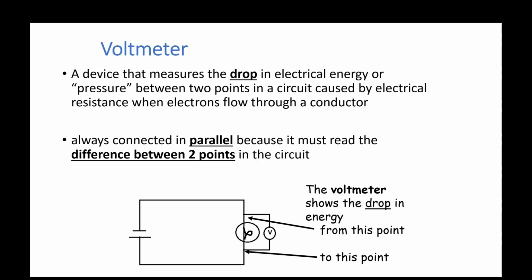the first question on one of the circuit diagram worksheets that you were given before this had a very simplified circuit like this. A lot of you thought it was a parallel circuit because the voltmeter was placed in parallel, but this is just a simple circuit. The voltmeter, however, is placed parallel to the load because it measures the difference in potential energy over here to over here.